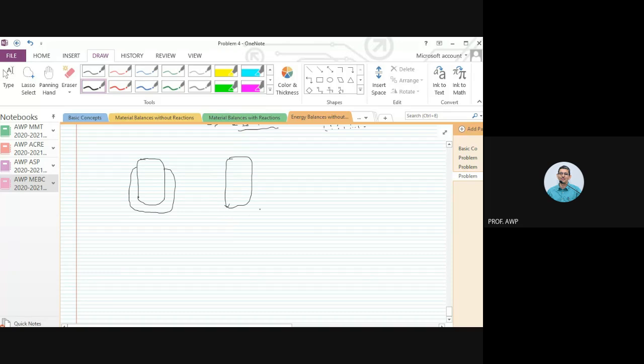Let's consider only two evaporators, so that it is easier for me to draw and easier for you to see. Here we have a 3% by weight NaCl solution, seawater. This is our steam. This is our condensate. This water vapor is going as a heating medium in the jacket of the second evaporator. I will get condensate from here as well.